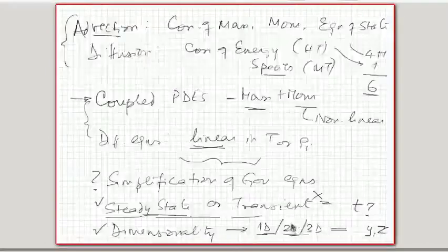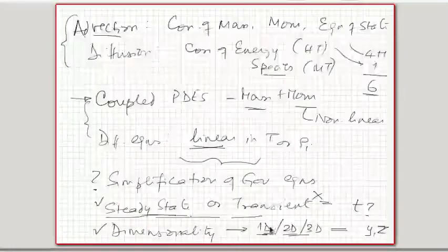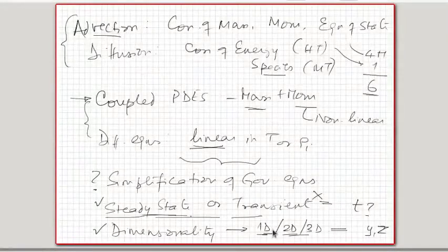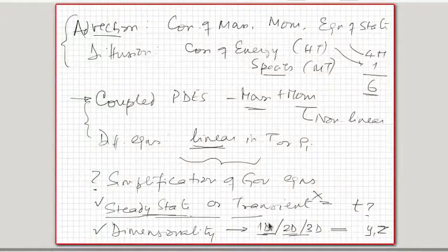Sometimes it also happens that there is a similarity, that is, the temperature distribution, for example, may look like a particular shape, and that shape varies with the other direction. Say, for example, T versus y has a certain shape, and this just has a scaling factor as you go with x. So if you divide it by the scale factor, then the temperature profile with y at all x values will collapse to a single profile. That is called similarity.